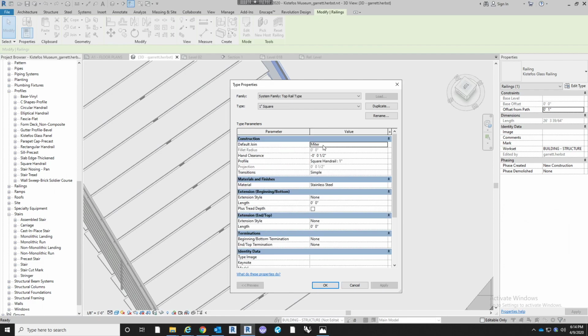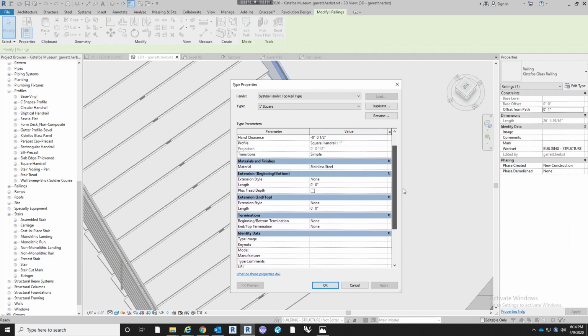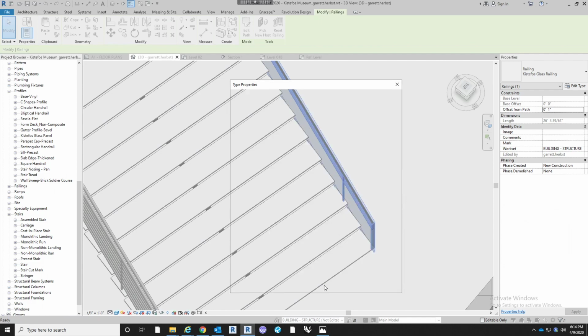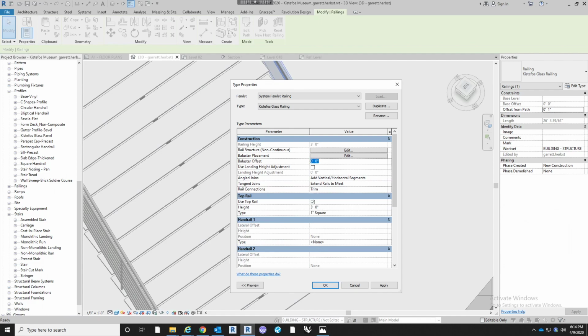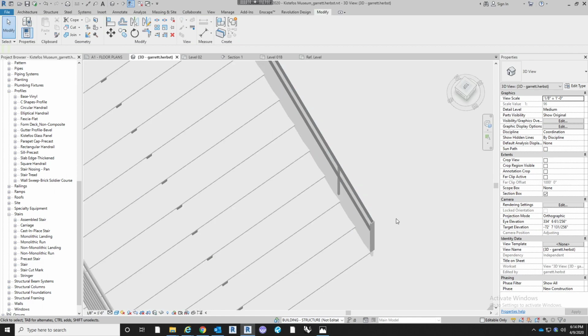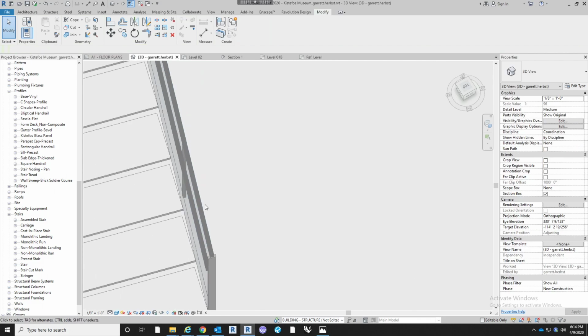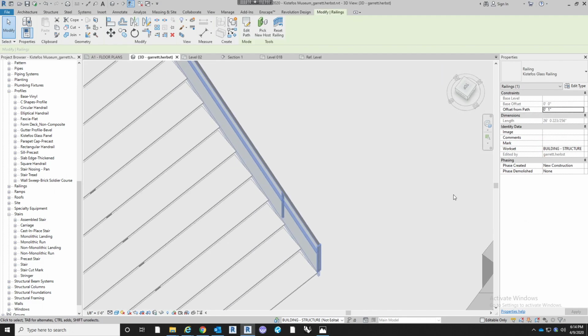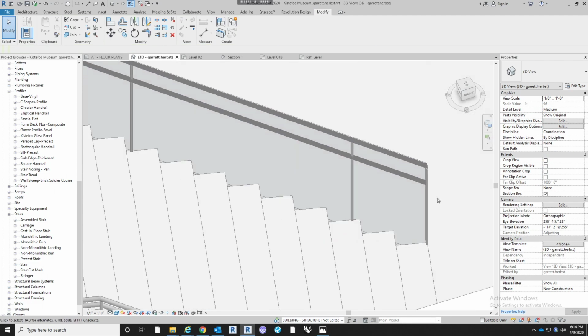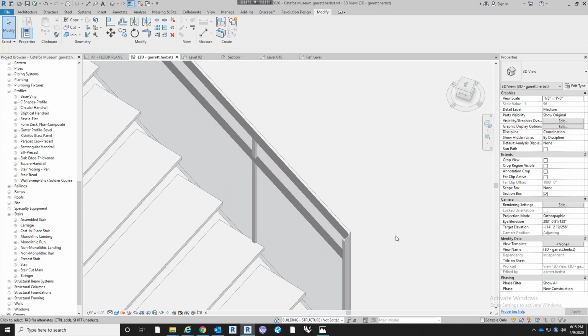So go down. What is an offset for this guy? Oh, baluster offset. 2 inches. Here, -2 inches, excuse me. It's -1. It'd still be touching. All right, and then I promise this is the last thing we'll do. So create a nice custom sleek stair. Of course, you can continue to edit that as much as you want.